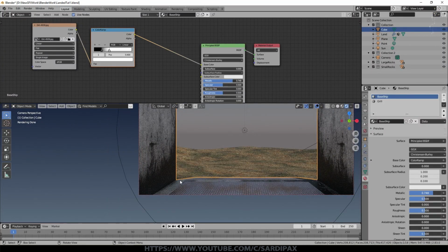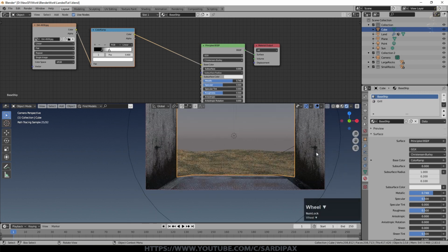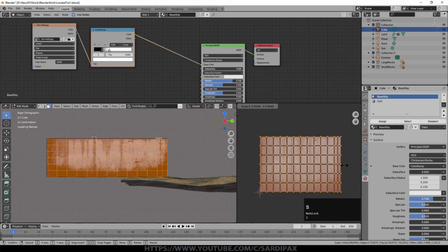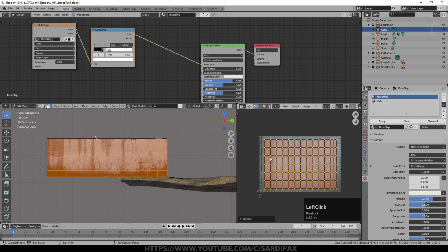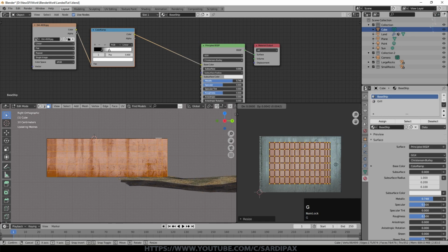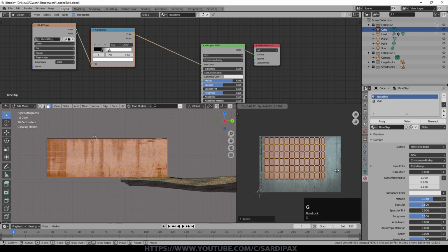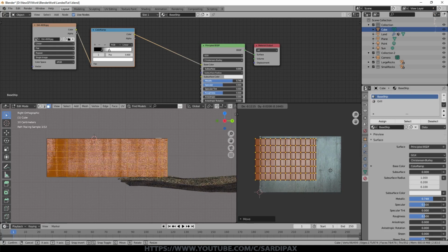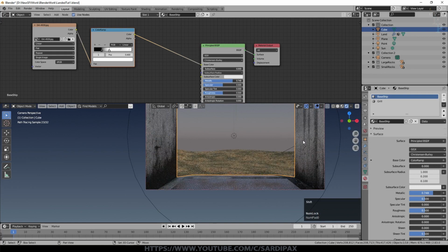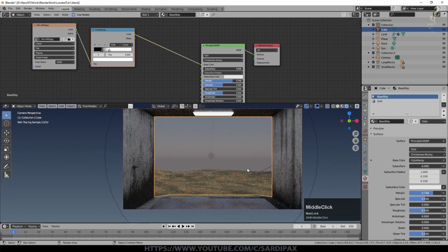I haven't properly set the UV map's position relative to the texture down here, but it probably doesn't matter too much. And the fact that it's identical one side to the other, obviously you can fix that by just moving one of the UV maps around. I think I'll do that now just to show you, because it's so obvious. I'll rescale it slightly and perhaps just move it off a bit. This is where it's better not to use the whole texture, and then you can move things around more easily. And generally I wouldn't want to run the end off like that. So I just flipped it round as well. And now if we look through, you can see we've got very different textures one side to the other.